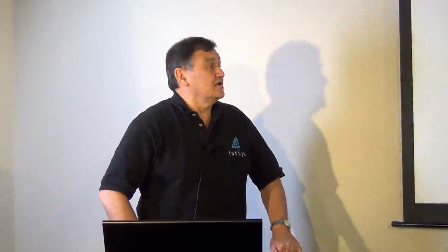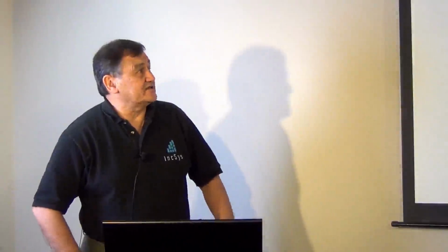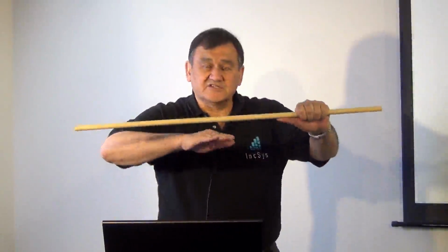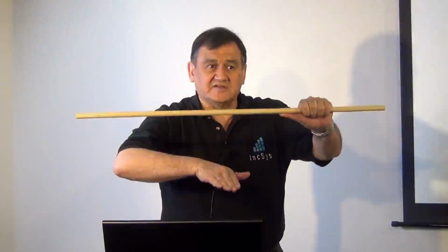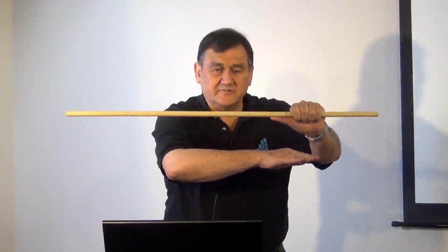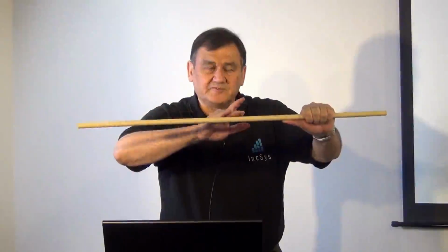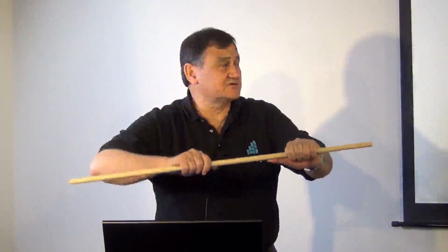All right, so looking in a little more detail at a simplified diagram for a transmission line. Basically, there's a reactance effect because, like we said, those conductors have magnetic fields, and we represent that as a series reactor. Those conductors also have a capacitance effect. The conductors are in parallel, and based upon the conductors being closer and closer to each other, you can have a buildup of electrons on one versus the other. Again, all this is happening at 60 cycles per second.